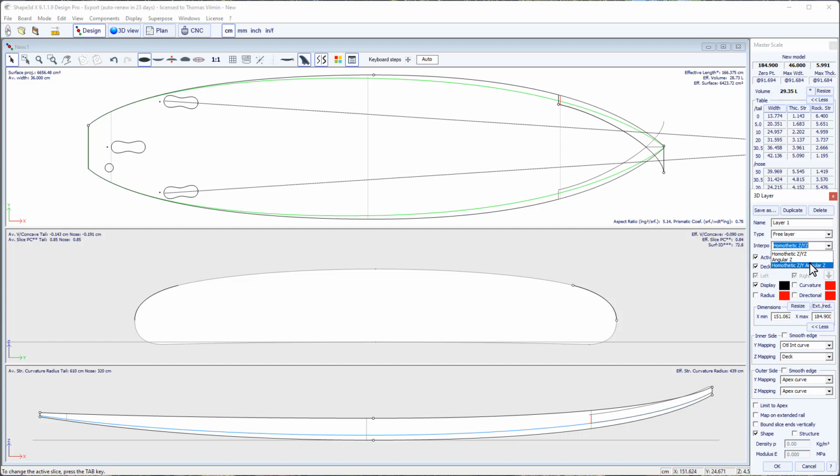And it's not very easy to understand at first, but you see, most of the time, homothetic is the good way to do, but in some cases the height of the inner and outer side of the 3D layer goes from positive to negative, and in this case the homothetic mode will completely reverse your 3D layer, and in this case you will prefer the angular mode just to rotate the slices and keep the shape.